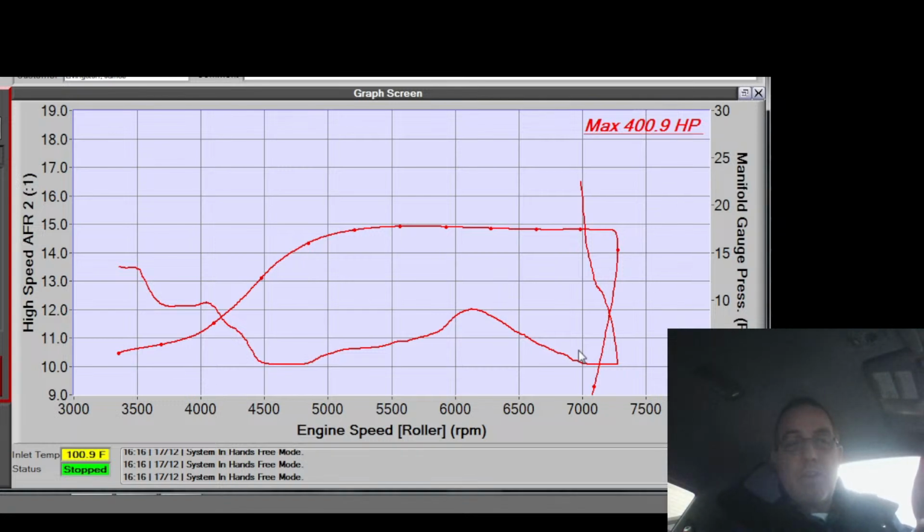We're letting it get hot out there. And then the closer we bring it to, or the sooner we bring it in contact with, the body of the plug, which is in contact with the head, the sooner that gets cooled down, or the more it gets cooled down, I should say. The less heat temperature delta we have on that piece of metal dangling out there in the chamber. So the first thing is that it has to be hot enough to clean. It has to get hot enough to self-clean.